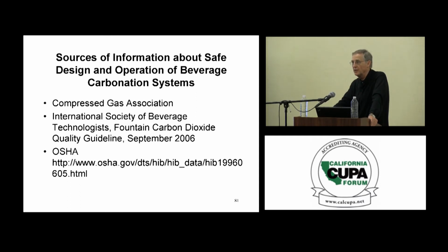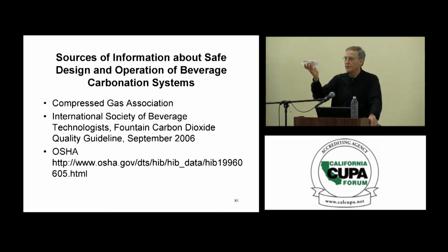It has to be at less than minus 90 degrees C for it to be a cryogenic fluid. Do you mean less than minus 90? Yes. Oh, okay. Because that's where I was having confusion as well. Is it the boiling point less than a certain temperature? No. Or is it the storage temperature? The storage temperature. It's the physical temperature of the liquid. It's what it's stored at.